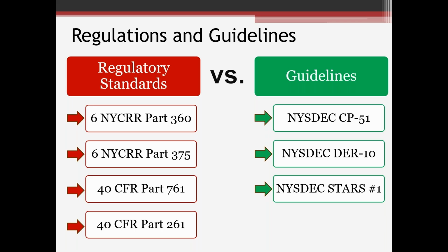Part 375 we'll go over a little bit, but that contains a lot of the soil cleanup objectives that we're striving for. Then there's 40 CFR Part 761, the PCB mega rule, which has provisions on sample analysis of PCBs. And 40 CFR Part 261, the hazardous waste regulation, which helps with sample analysis for hazardous waste determination.